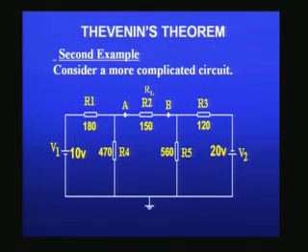Here as you can see, it has got two sources, there is V1 here 10 volts and V2 here 20 volts, and you can see the polarity is also changed here, and you have a number of resistances R1, R2, R3, R4 and R5, and this R2 is actually RL, I assume, and therefore what we want to do now is find out what is the voltage across R2, A and B. R2 is our RL, I have shown here. So, we want to know what is the voltage across this.